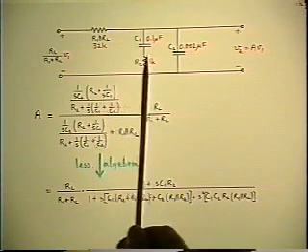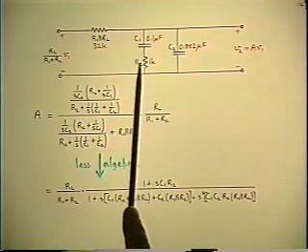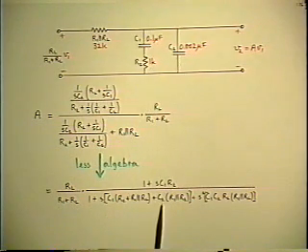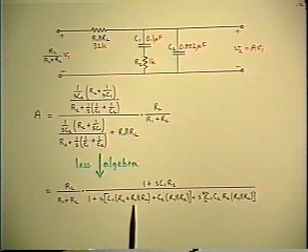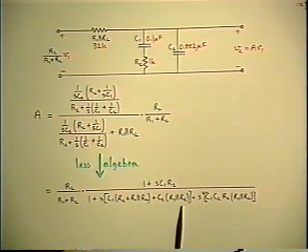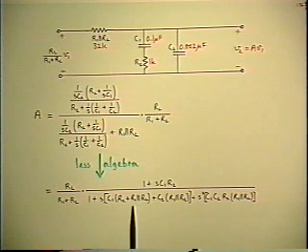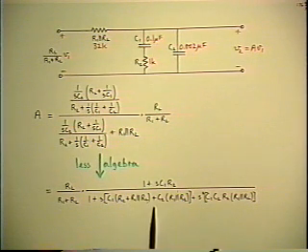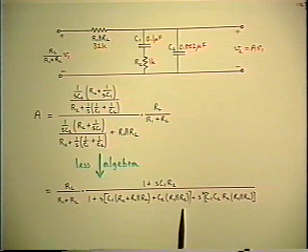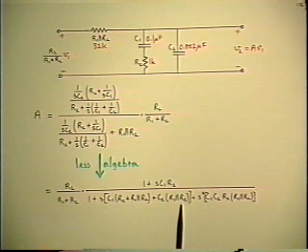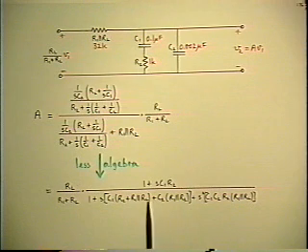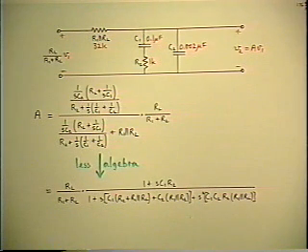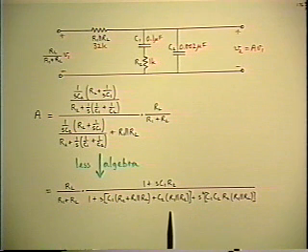And when you look at the tentative set of values, you see that the C1 is 50 times bigger than C2. And associated with the C1 is a resistance which is bigger than the resistance associated with C2. So both of those effects go in the same direction to make the C1 term even more than 50 times bigger than the C2 term. So there is less than a 2% error in neglecting the C2 term. And you can see all that without actually going through the substitution of any numbers, because you can do that in your head easily enough.